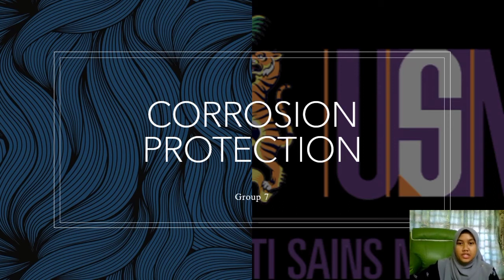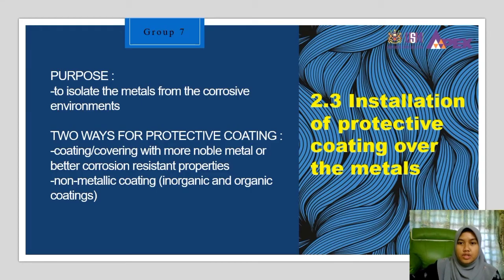Today I would like to present about the corrosion protection. So first, installation of protective coating over the metals. The purpose is to isolate the metals from the corrosive environment. There are two ways for protective coating, which is first, coating or covering with a more noble metal or one with better corrosion resistant properties, and second, non-metallic coating, which is inorganic and organic coatings.